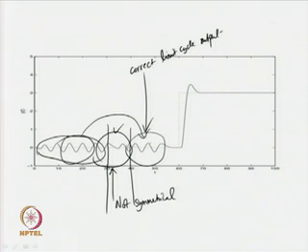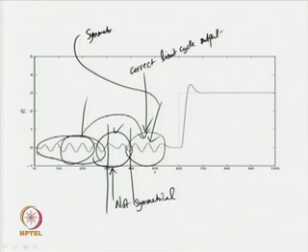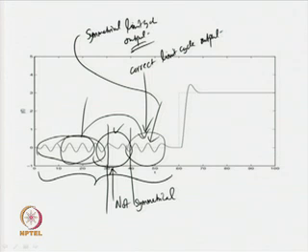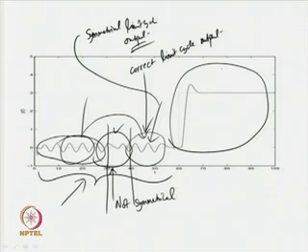Now, the measurement should be made either from here or from here. It does not matter; you have to target symmetrical limit cycle output. So, target the symmetrical limit cycle output, consider a few cycles and make measurements from the stable, symmetrical output signal. Then when the tuning phase, or auto tuning test phase, is over, the relay is switched off. Then you get the normal operation of the system, and if you have tuned the controller properly, the controller provides proper dynamics of the closed loop system.